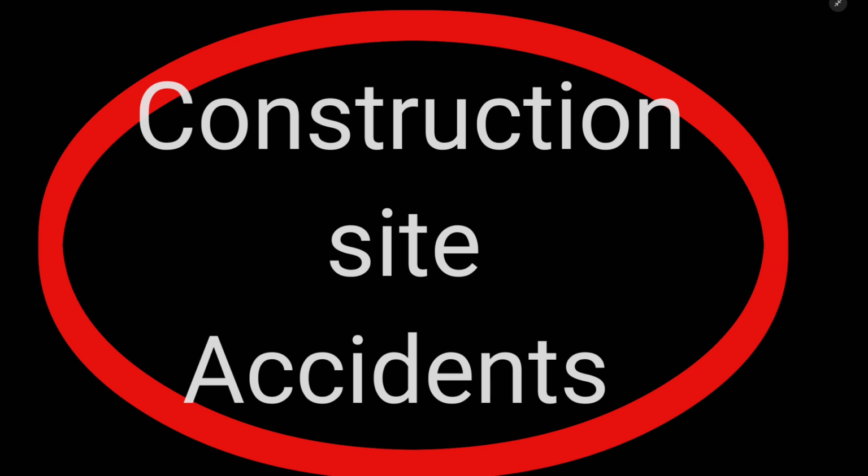Eighth is exposure to hazardous materials. Exposure to hazardous substances like asbestos, silica dust, or lead can lead to long-term health problems. To protect workers, provide proper PPE such as respirators, gloves, and eye protection. Always follow safety data sheet for handling dangerous materials.